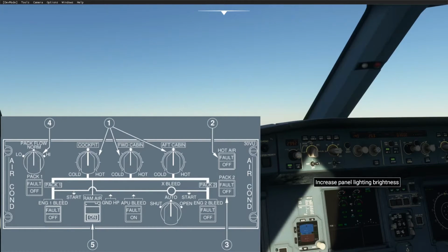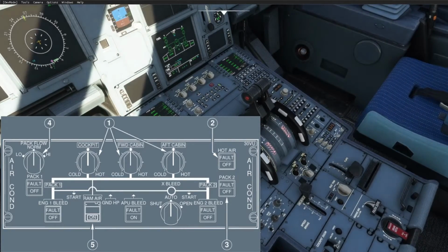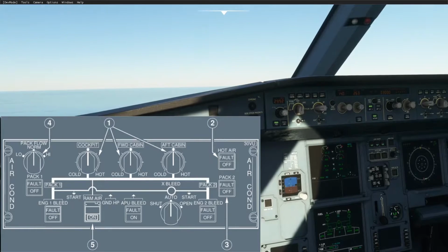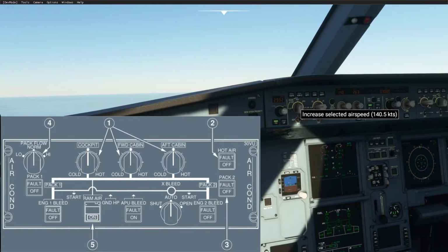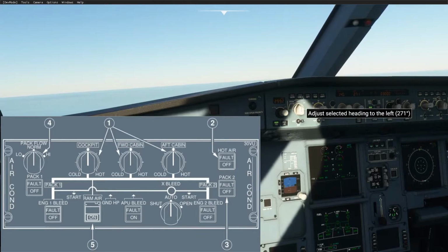And there's a pack flow selector, which we use in the event that there's low passenger numbers. We'll select low. In an Airbus A319 or A320, you're looking at about 130 or less, or an Airbus A321, you're looking at 160 or less. However, in these troubled pandemic corona times, we normally have it on high to enable maximum ventilation in the cabin.